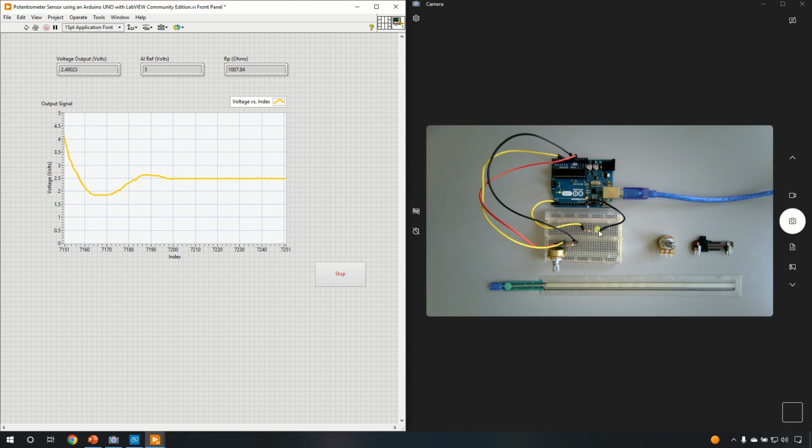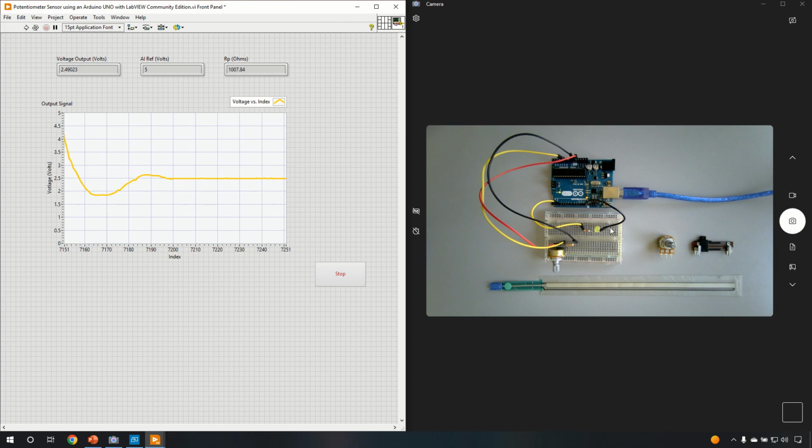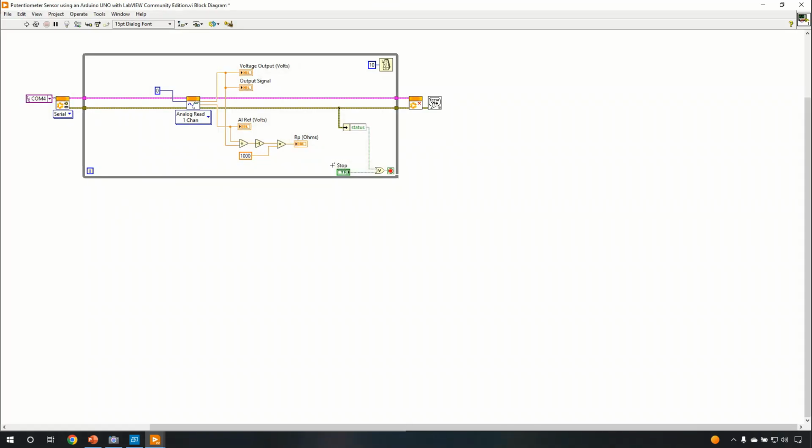Now the final thing that we need to do is to really correlate these voltage values to a PWM or duty cycle value in order to control the brightness of this LED through the Arduino. So instead of connecting this LED to this circuit right here, we'll have two different circuits, and what we are going to do, we are going to correlate the values of voltage inside LabVIEW to a duty cycle voltage. So here's what we are going to do.